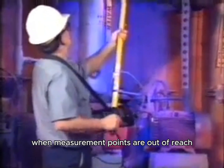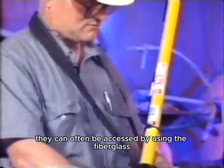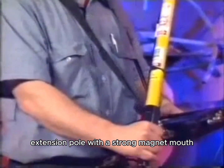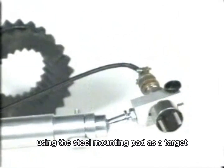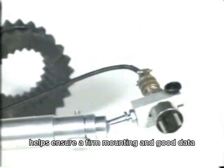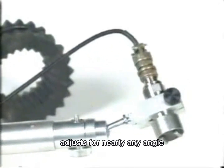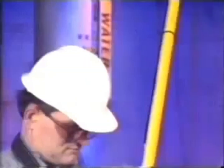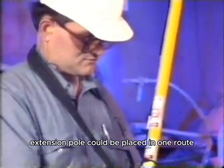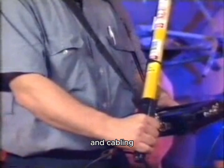When measurement points are out of reach or are unsafe for personnel because of temperature extremes or environmental considerations, they can often be accessed by using the fiberglass extension pole with a strong magnet mount, such as the CSI 906 or 908 super magnet on the sensor. Using the steel mounting pad as a target helps ensure a firm mounting and good data. The swivel head of the extension pole adjusts for nearly any angle. Sensor grips are available for most common size sensors. All the measurement points that require the extension pole could be placed in one route to avoid the loss of time for changing the sensor and cabling.